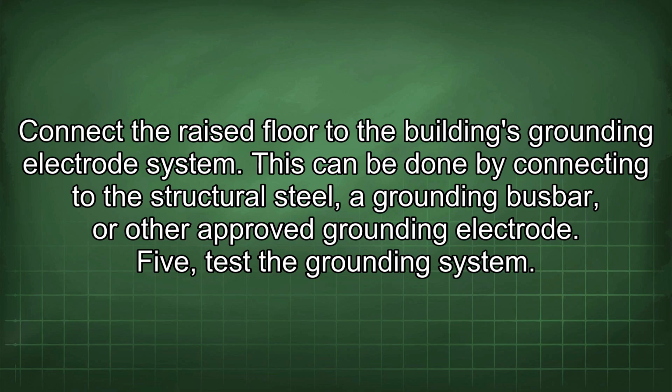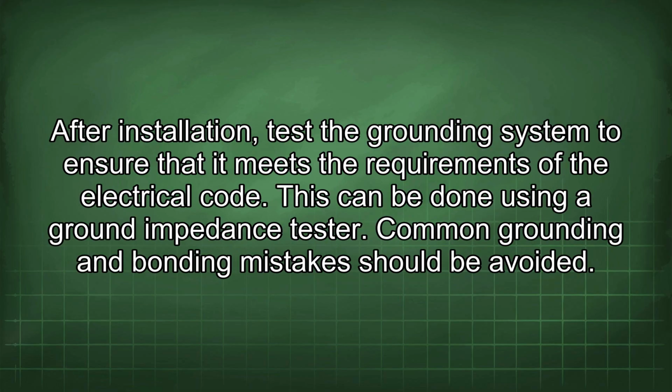5. Test the grounding system. After installation, test the grounding system to ensure that it meets the requirements of the electrical code. This can be done using a ground impedance tester.